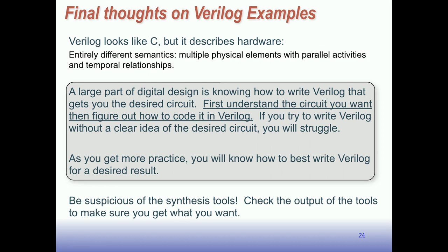I always start with paper and pencil, and I draw out the circuit I want, and then I figure out how to write the Verilog. If you try to write Verilog without a clear understanding of your desired circuit, you're going to get in trouble. You'll get code that's hard to debug and may not do what you want, and it may not be very efficient. I say this all the time, and I see people getting in trouble all the time because they're faced with a problem and immediately start writing Verilog, rather than sitting back, pausing for a minute, thinking about the circuit, and then figuring out what Verilog will give you that circuit.